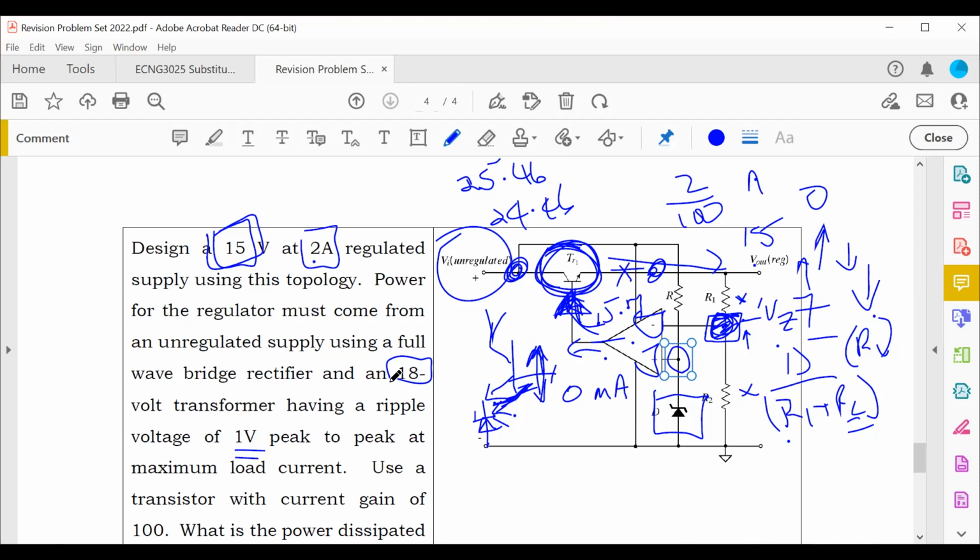So yeah, that makes sense. You put a fuse on the primary, so the wires won't burn. Yeah, exactly. You put a fuse on the primary side of that 18-volt transformer. You put a fuse there, and if you want, you put a fuse on the secondary side as well. Hard and fast: you short circuit or you go over the 2 amps or 3 amps, and it will blow the fuse. It's not regulated. It's not overcurrent protection, but in fact it is one-way overcurrent protection. You blow the fuse, so you have to go and fix the fuse to get it to work again, kind of. But it wouldn't burn any wires or anything.